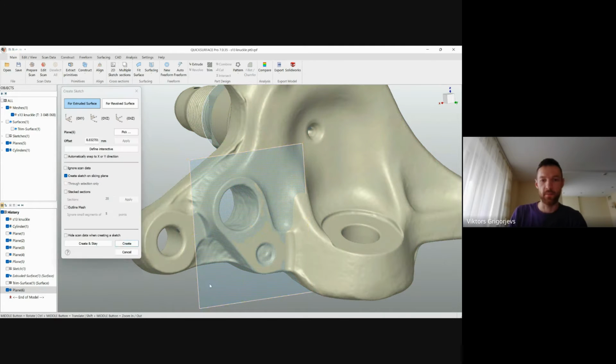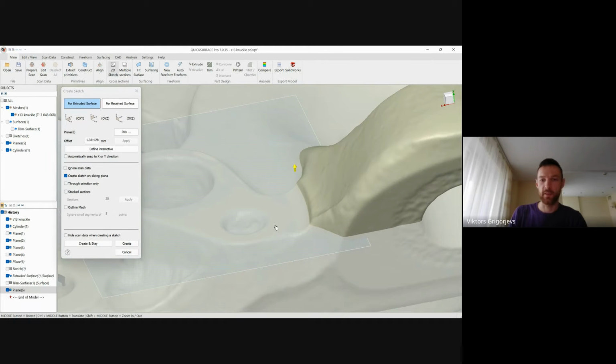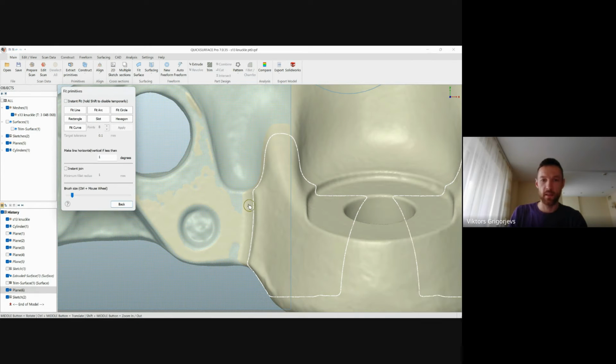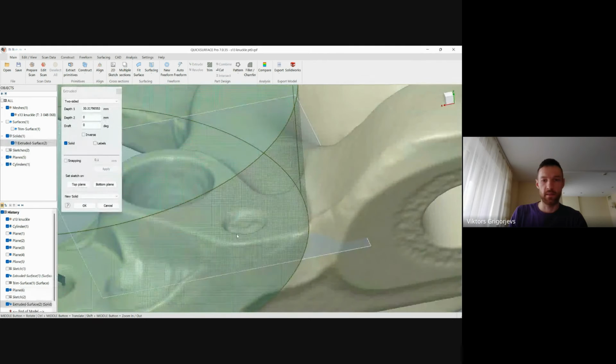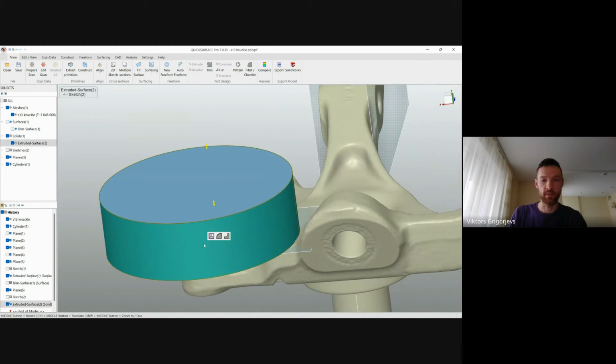Okay, and going with a mesh sketch just to define the circle again here. This time I create it as a solid, because we can use our circular surfaces as reference points for our revolving mesh sketch.